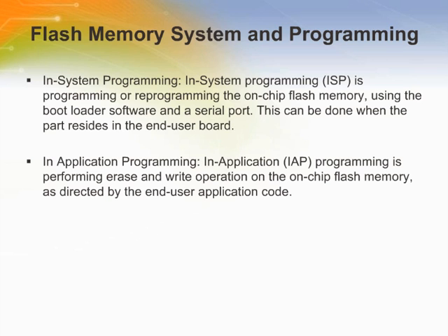The bootloader controls initial operation after reset and also provides the means to accomplish programming of the flash memory. The flash bootloader code is executed every time the part is powered on or reset. The loader can execute the ISP command handler or the user application code. A low level after reset at the P0.14 pin is considered as an external hardware request to start the ISP command handler.